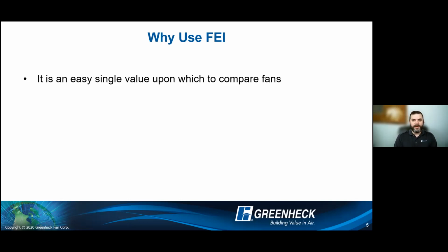So I'm looking at all those things, and I'm trying to rank these fans in order, and trying to grab the best one, the right one. Since FEIs have been implemented, I can simply look down a column and have a quick reference on, is this a good fan and a good selection for my application?